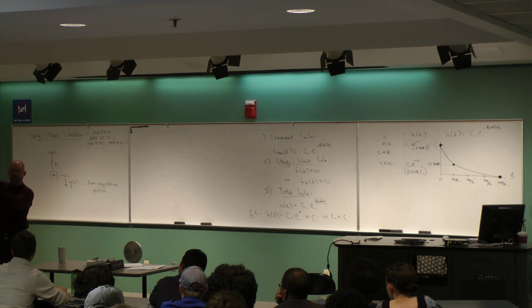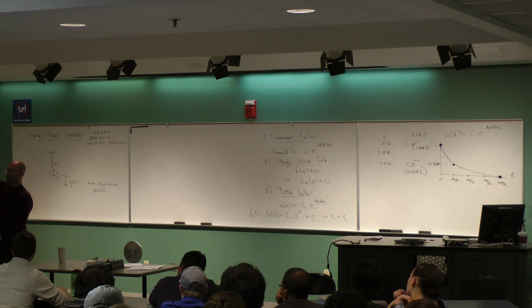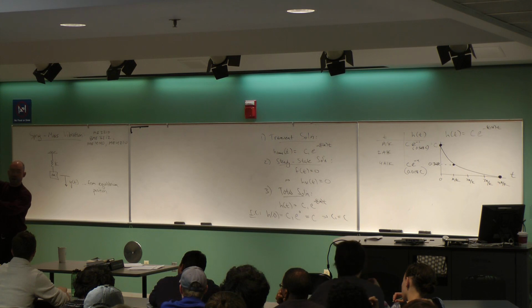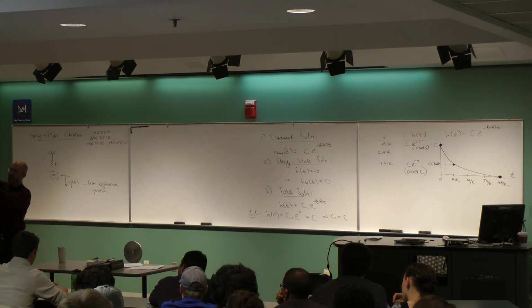Here's the undeformed length of the spring, and at t equals 0, I just let it go, because I have initial energy dumped into it because it free falls for a little bit. So if I start at equilibrium, that means the spring is balancing the weight. And if I displace it from equilibrium, that becomes the midpoint now. It just oscillates above and below that. So essentially the whole problem ends up just shifted if I start here, and then bam, now it's oscillating below, so the whole thing's just shifted.